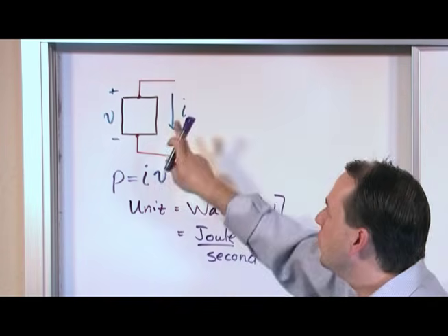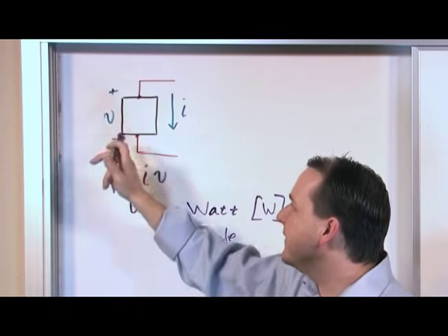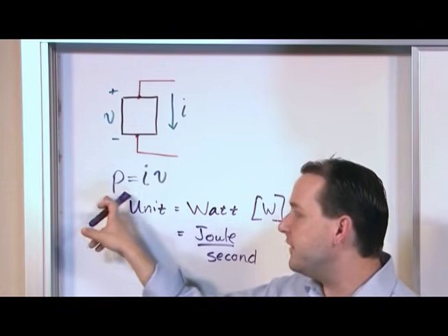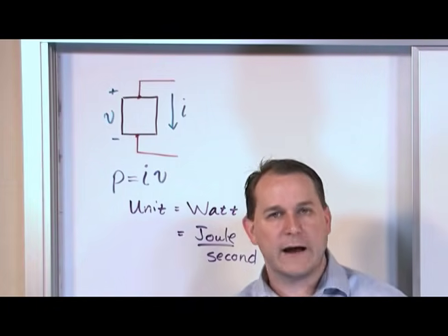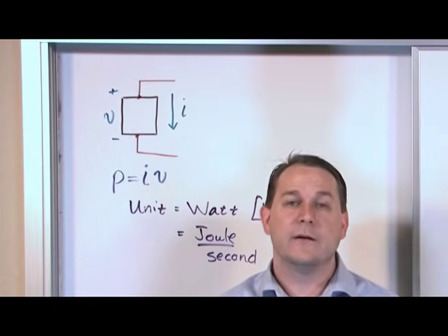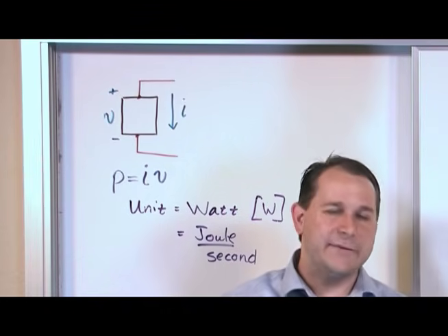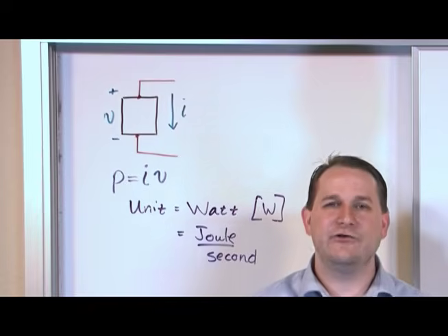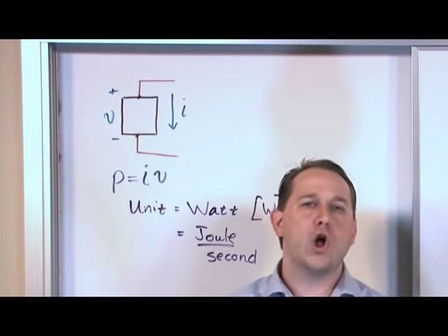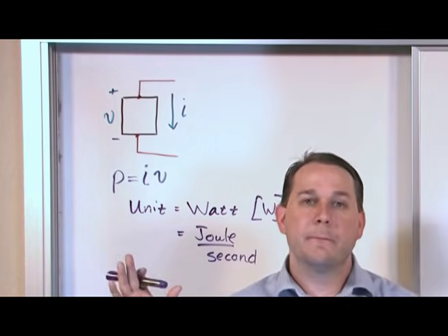So later on, when we draw a complete circuit with a voltage source over here, what we're going to find is that this circuit element over here, which could be a resistor, has positive power greater than 0. That means it's absorbing power, right? Getting hot. The source over here, you calculate the power by that guy, and you're going to get a negative power, right? And that negative sign doesn't mean anything mystical. It just means that that element is delivering power to the rest of the circuit. So all of your sources should have negative watts, and everything else in the circuit should have positive watts.